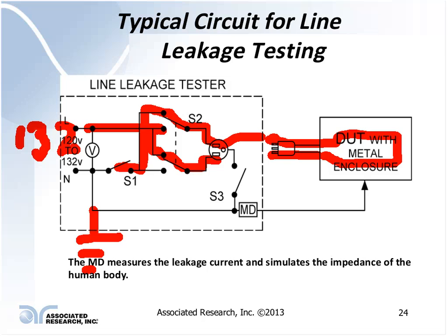So now I have no return path. So all this circuit is at 120 volt potential in relationship to this earth ground. This creates the highest leakage current in my device, just due to capacitive coupling of all the circuits. My circuit from my hot side.